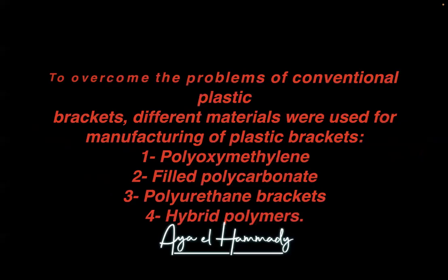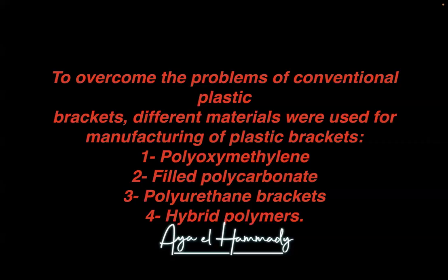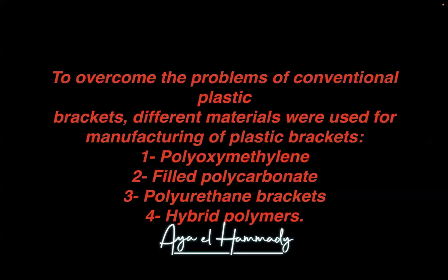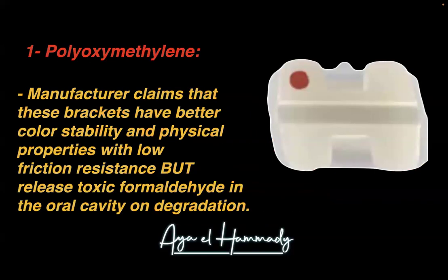First of all, I have a problem with the plastic one, okay? So I need, first of all, to overcome the material problems, okay? By using one of the following, like what? The polyoxymethylene, the filled polycarbonate, polyethylene brackets, and the hybrid polymer. So let's dig more into this, okay? The polyoxymethylene, what will happen? Okay, it has better color stability. Write it down, please, after me, Rahim. This is very important in your exam, okay?